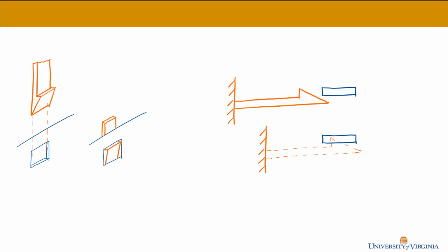It can't be in that position because it's going to interfere with the blue piece of material. And so the snap's going to have to bend. And the snap will bend down like this. And then if we keep pushing it to the right, then it'll reach a point where it makes it to that notch, to that hole in the blue material, and the snap fit will snap back up because it has that elastic property where it bends and then it bends right back to its original position because it's in that linear region and it hasn't gotten to a point of its ultimate tensile strength or flexural strength and breaking.